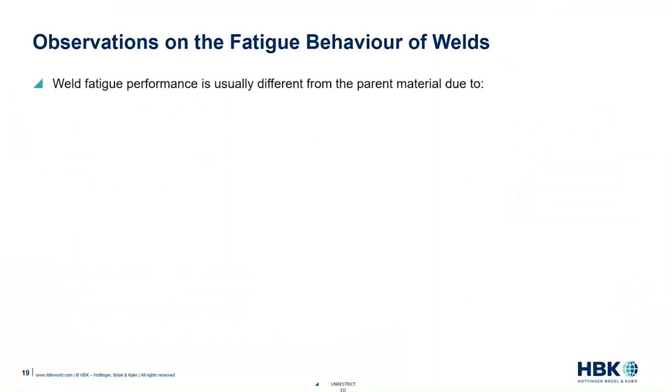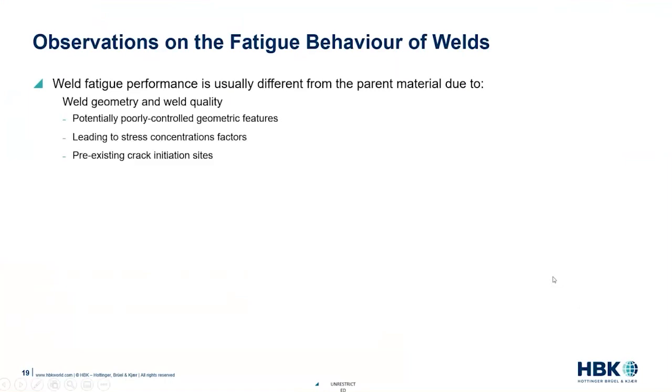First, some observations on general fatigue behavior of welds. Weld fatigue performance is usually different from the parent material for many reasons. The weld geometry and the weld quality can lead to stress raisers and stress concentrations. The difference between the smooth CAD profile of a designed weld and the reality of a manufactured weld.